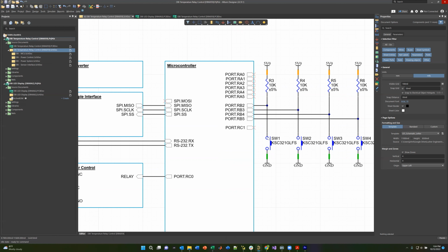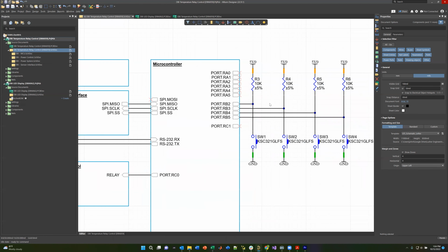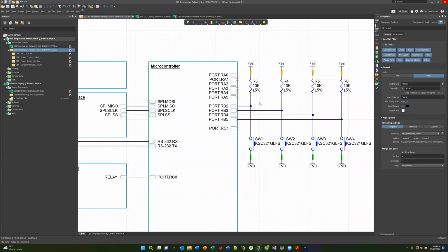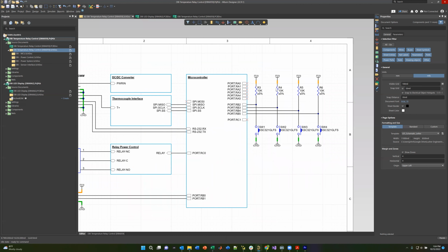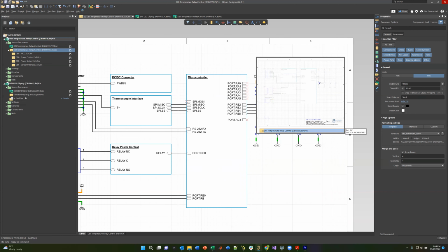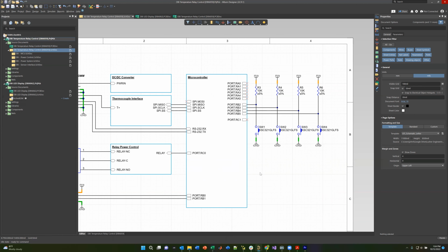If the switch is pressed and there's now current flow through to ground here, the voltage at this terminal obviously will be ground. So basically we're making a 1 or a 0. Many years ago, you would have to do a circuit called a switch debounce because when you press momentary switches, or any switch, there is mechanically what is known as bounce, where it will make contact, no contact, contact very quickly in microseconds time.